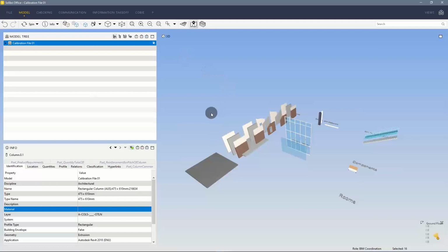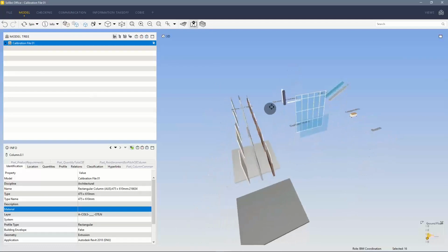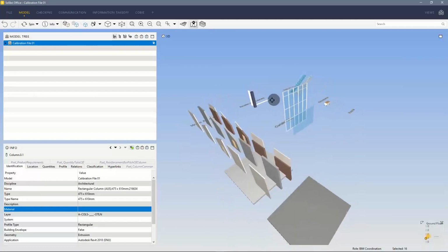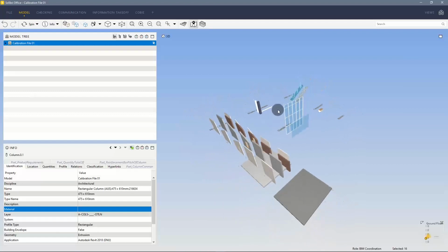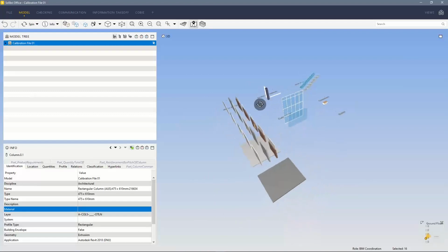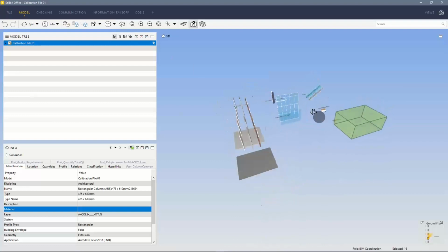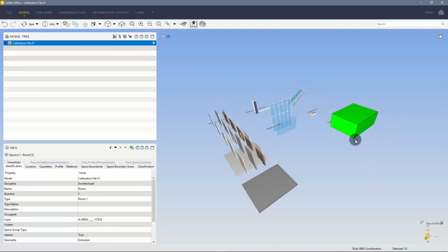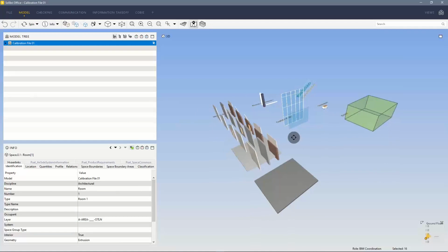Now that I have it in there, you can take a look at what they have produced. Make sure that everything is in place. In case you're using a regular or neutral IFC viewer, in most cases, spaces and zones will be hidden. So I'm just going to switch that on to make sure that it is there. And then once you have it here, the two things you will be looking for to validate the file before you bring it into Archicad are essentially two things.